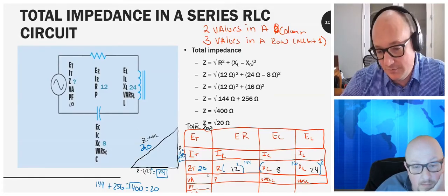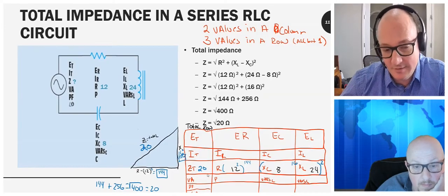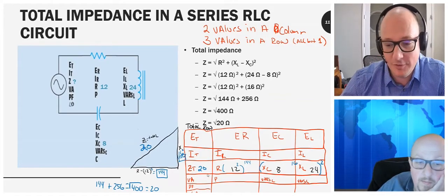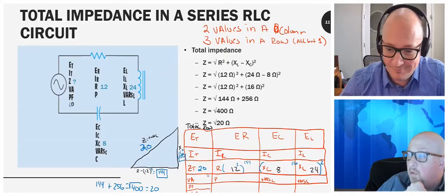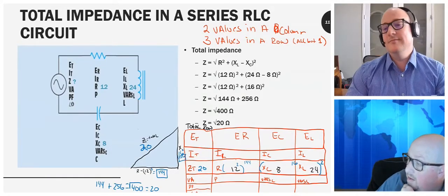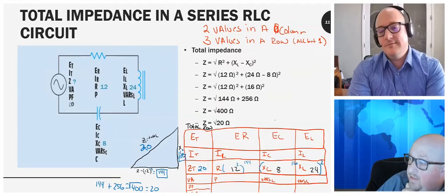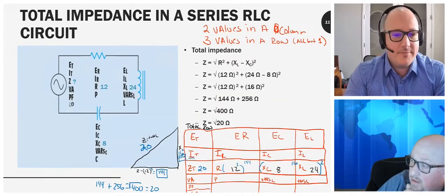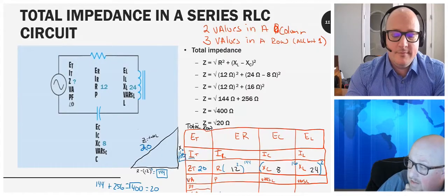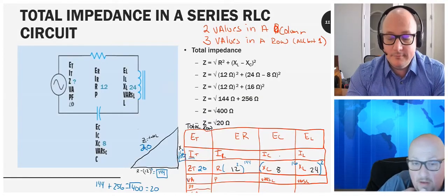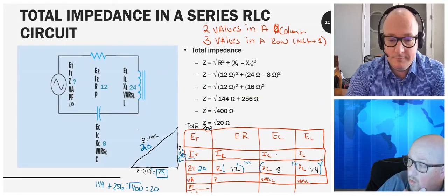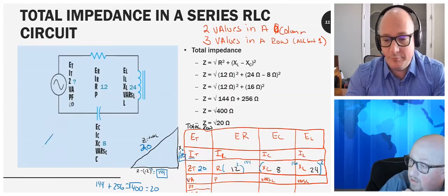And then we could solve the rest if we were to give it a voltage value, say we applied 277 volts nominal, a pretty typical system voltage. But before I get into that, I have a question for you. That same exact math works in a series circuit on current and VA. I use the right angle math. So if I were to be given only current, I should be able to do the same thing exactly, right? I would have another hypotenuse.